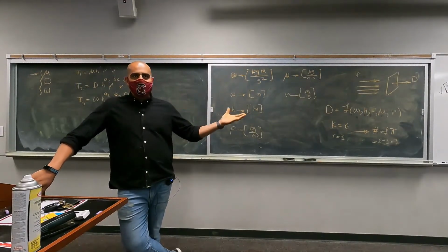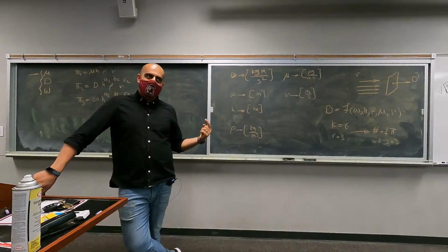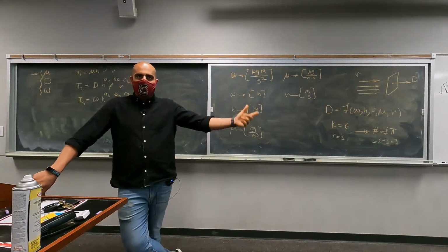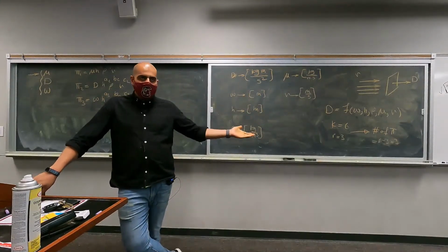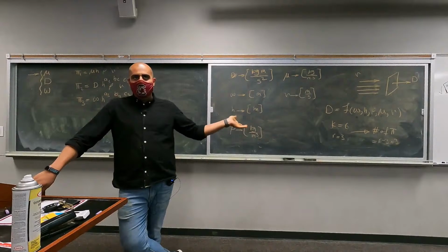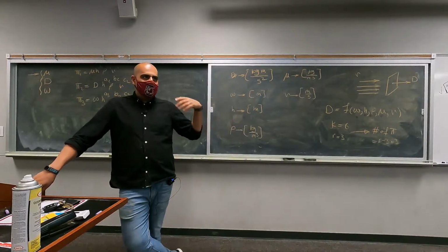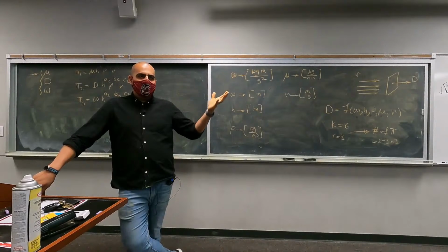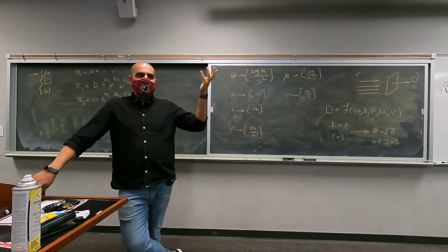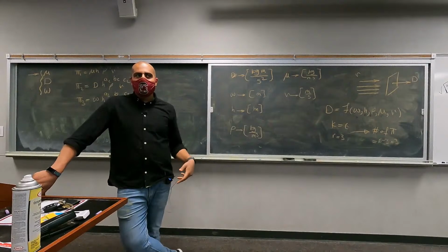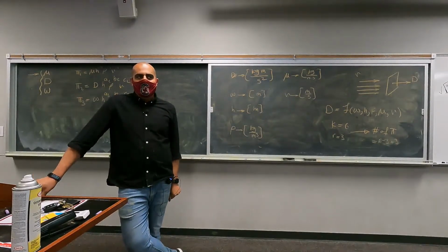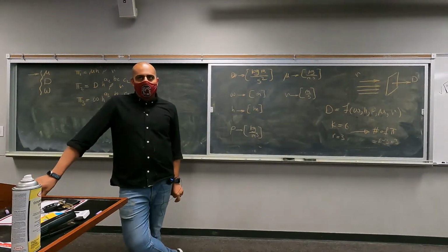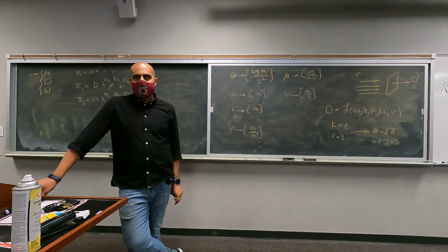You have pressures at 2 points, velocity at 1 point, you can find the velocity at the other point. That's what Bernoulli does, right? Whenever you're given this type of problem, use Bernoulli. Whenever you're asked to find the pressure needed to change the volume, that's the compressibility problem. You want to get to the bulk modulus. So we are going to focus on these types of things a little more. Okay?